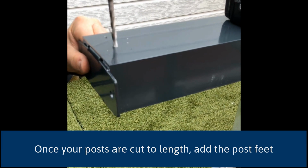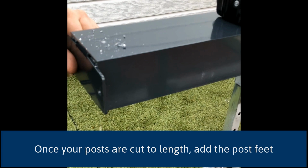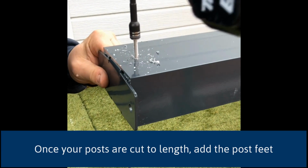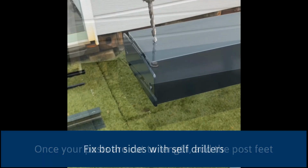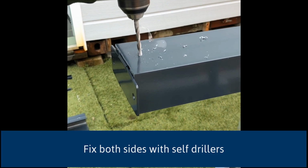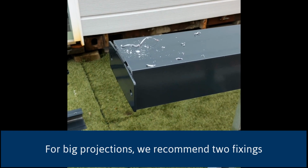Using a self-driller, drill a pilot hole through the post itself. Using a self-driller, fix the footplate as shown. Please ensure you have a fixing both sides. For big projection canopies, we recommend 2 fixings.